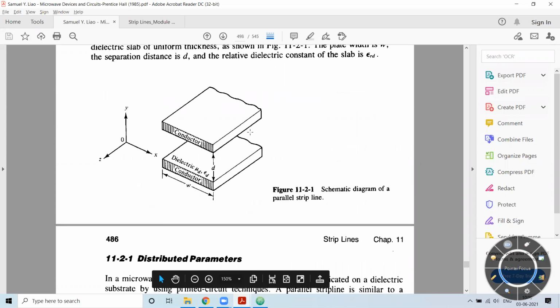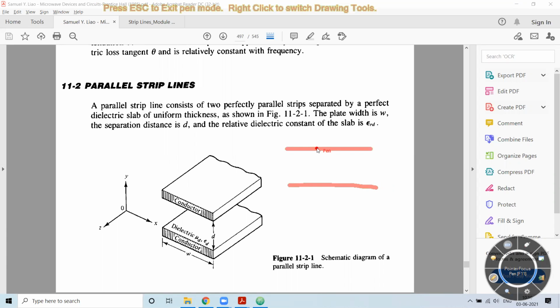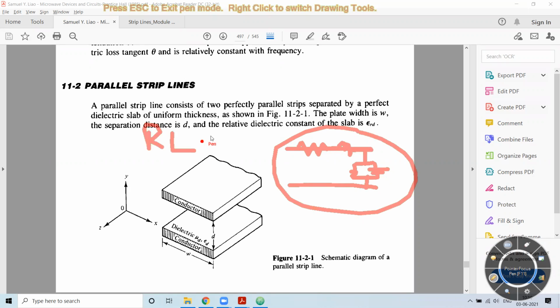Now, as I just specified, this is nothing but two lines placed parallel to each other. In the previous session, we discussed that along the transmission line we have the impedance parameter, and along the parallel path we have the conductance parameter and the capacitance parameter. So these are the distributed elements, that is, we have RLGC parameters which are distributed over the transmission line.